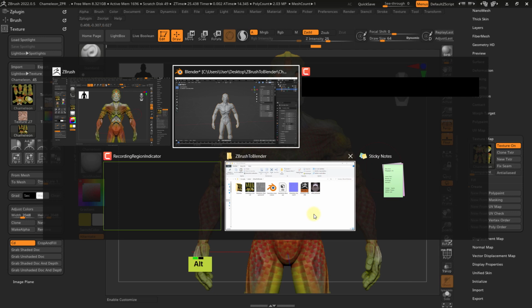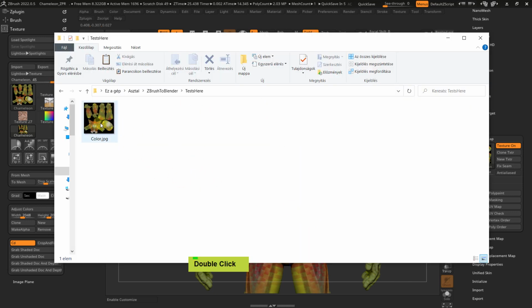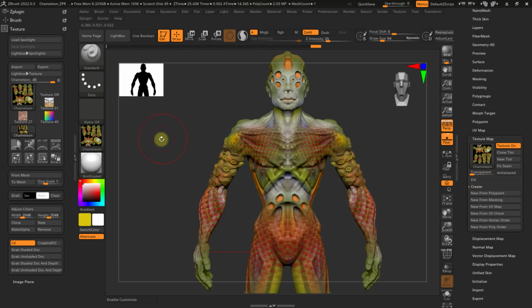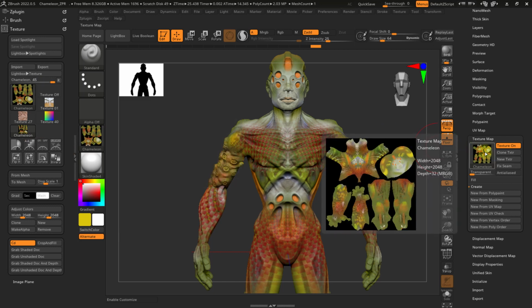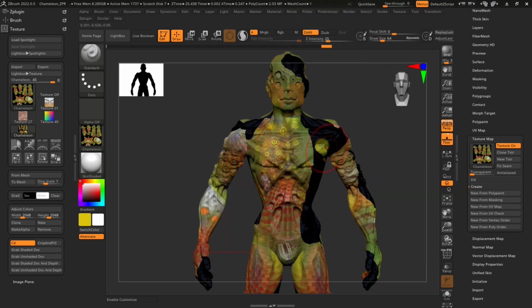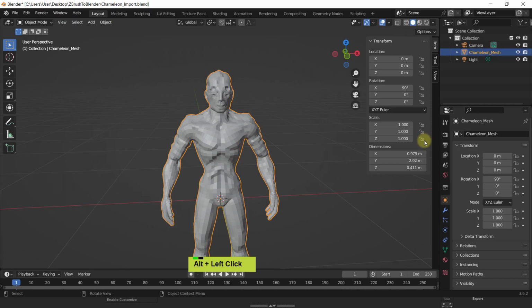And then we have the properly flipped option. Okay, here don't get confused. Just because you have flipped the texture itself in here, it doesn't automatically update. This is like a buffer. So if you want to switch it, you have to come in here, pick again, and then it flips. Okay, so this is when you forget to flip. This may look like this in Blender as well. So now we have the right texture.